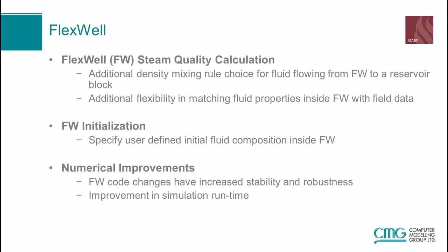On Flexwell initialization, we now have the ability of overriding what the default initialization would be, where it would typically decide the fluids and compositions, by being able to put in user-defined saturations and fluid compositions inside the Flexwells. So you can actually start the well off with the fluids that you would expect to be there based on your completions or how it should be defined. And they've also done quite a bit of work in terms of overall numerical improvements, meaning that the Flexwell has had code changes that have increased both the stability and the robustness in order to improve the overall run times when you're running with Flexwell.